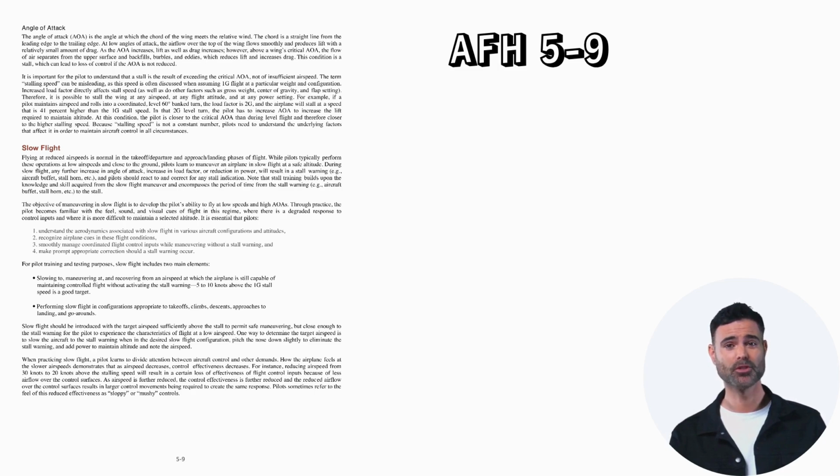Slow flight. Flying at reduced airspeeds is normal in the takeoff, departure, approach, and landing phases of flight. While pilots typically perform these operations at low airspeeds and close to the ground, pilots learn to maneuver an airplane in slow flight at a safe altitude. During slow flight, any further increase in angle of attack, increase in load factor, or reduction in power will result in a stall warning, e.g., aircraft buffet, stall horn, etc., and pilots should react to and correct for any stall indication. Note that stall training builds upon the knowledge and skill acquired from the slow flight maneuver and encompasses the period of time from the stall warning, e.g., aircraft buffet, stall horn, etc., to the stall.